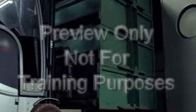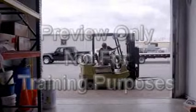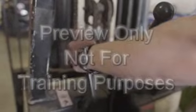Come to a complete stop before changing directions and use a horn or warning light to warn pedestrians when reversing. Do not park in unauthorized areas or block aisles or exits. Set the parking brake when stopping.